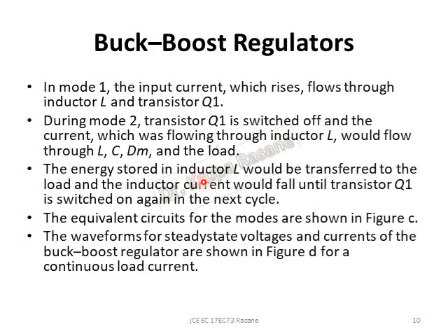So the energy that is stored in inductor L would be transferred to the load, and the inductor current would fall until transistor Q1 is switched on again in the next cycle. So we'll see the rise in current in mode 1 and the fall in current in mode 2. The equivalent circuits have been shown to you, and the waveforms for the steady state voltages and currents of the buck-boost regulator are shown for continuous load current.